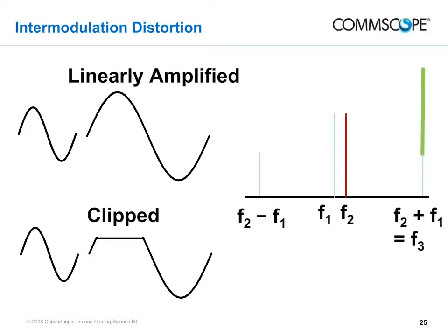But when the amplifier is either under or overdriven at the input, it will apply different amplification to different parts of the signal, or even not allow the signal value to rise above a certain value known as the clipping level. Diode junctions can also produce non-linearities. In RF circuits in particular, the diode junctions may not even be an intended part of the circuit. For example, to an RF signal, a corroded connector may effectively become a diode.